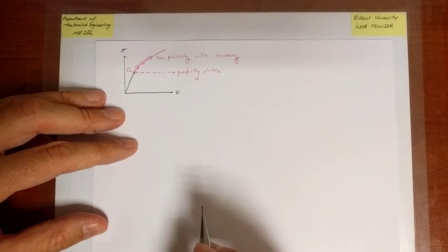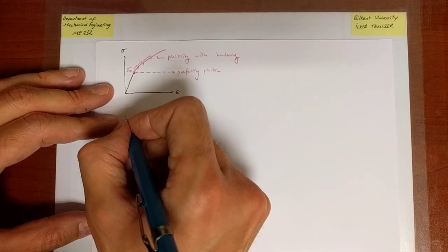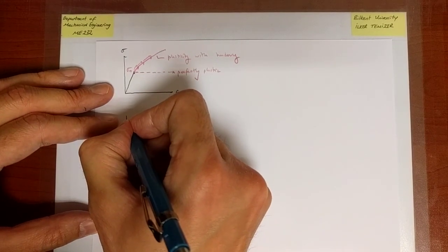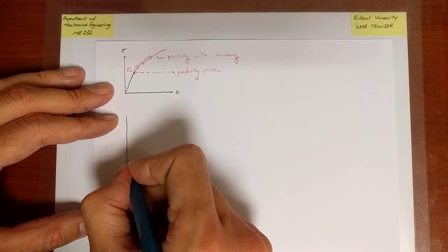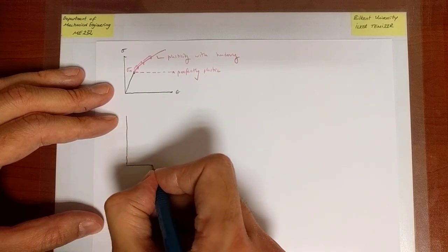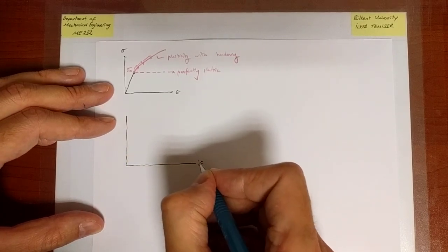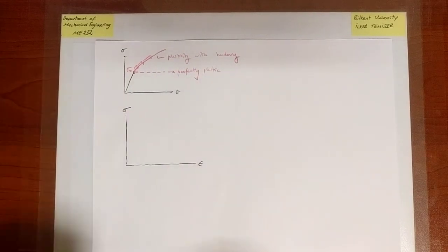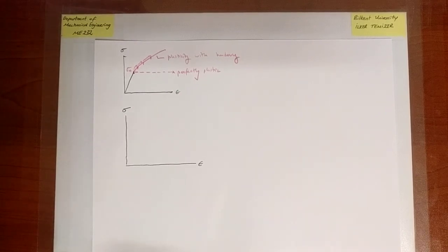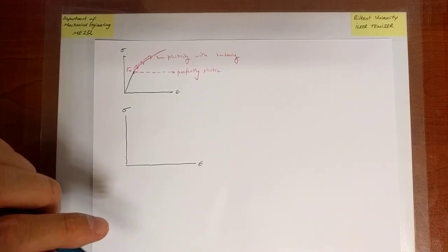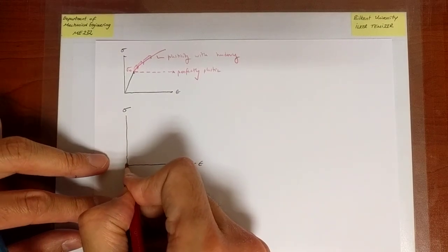So, well, how do I observe hardening and why is it important? Well, I can give you a very simple example that comes also from the stress strain curve. So what I'm trying to do here is emphasize that in reality, the material really becomes harder to deform as you actually go into the plastic region. To explain that, I'm going to take a specimen and call it the raw specimen.